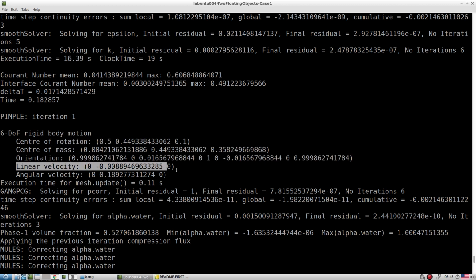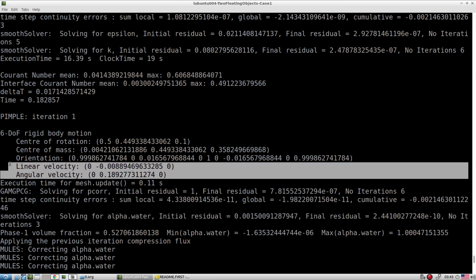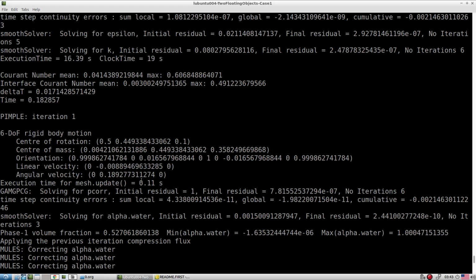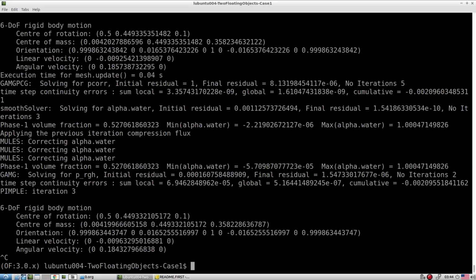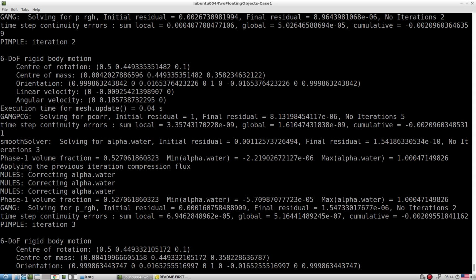Then linear velocity, we only leverage in the y direction, and we leverage the angular velocity as z direction, okay. So if we don't leverage this, then it tries to go in any direction, but we specify a particular constraint, and we say it's only able to rotate about the y-axis, and translation also with respect to y only. We don't want any other class of translations. That is what you are seeing from this, okay.